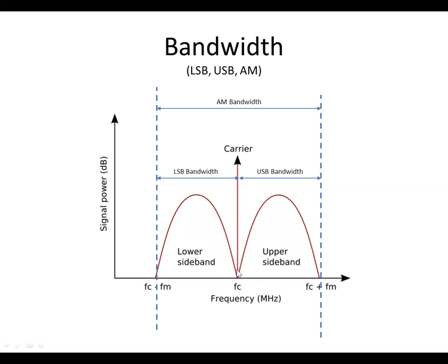And if you remember, we looked at a band scope on single sideband, and you were looking at the side lobes, the lower sideband and the upper sideband, and you could see that the waveform here on the lower sideband was changing with the voice. So it was transmitting the signal in time. When you looked at it in terms of the frequency, as the voice changed, the sideband changed, and that's how the information is sent.